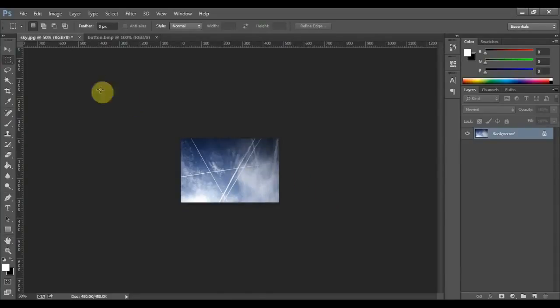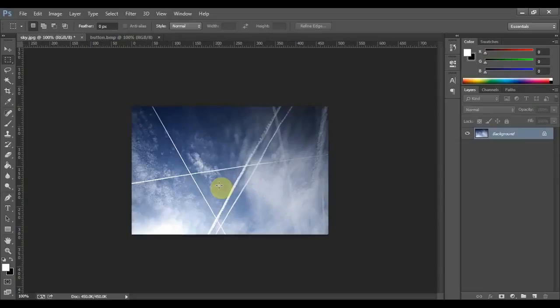Now our SGD43A, the width of it is 480, but the height of it is 272 pixels. So I'm actually going to reduce this image down a little bit further to get it to the exact same size as the SGD43A. So using my marquee tool here, I'm going to go up and change the style here to a fixed style. I've got the dimensions of the SGD43A, which is 480 by 272. I want to go and click down here on the artboard. That will select an area of the screen which is the exact size of the SGD.